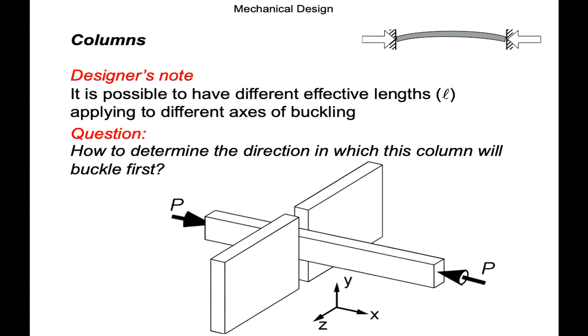Then it would be, you know, that argument I put before about it being really hard to get a perfect fixed end, or very hard to get a perfect pin joint. This object cannot just rotate. The blue cannot easily rotate in the realm of that slot. It can wobble a bit, it'd rattle, but it'd get to a certain point and then it would be fixed, as in fixed end. But let's not worry about that for now. Let's just think about it as being a pin joint.